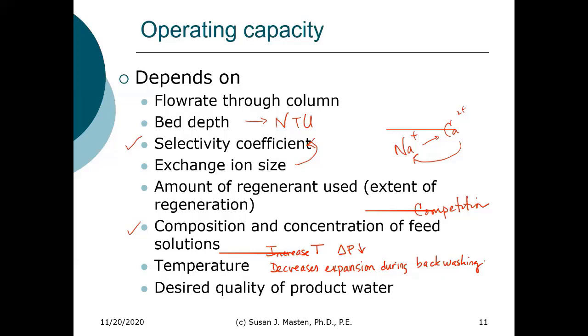So during backwashing, we will fluidize the bed, and that will help release any solid particles that were captured. It also allows for better regeneration. And backwashing can also help with removal of organics. And finally, the desired quality of the product water affects how much water we can treat to the point where we have to regenerate.